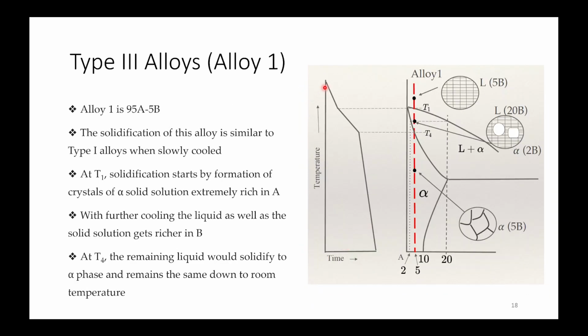Yeah, so this type of cooling curves are present, right? For each composition, for example, 10, 10.2, 10.3, all these compositions, you'll be getting that percent of steel you took, then you derived this cooling curve. Then you extended this cooling curve to get these lines.